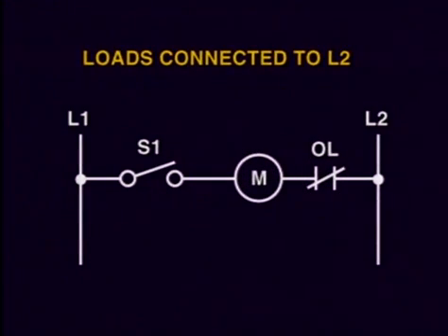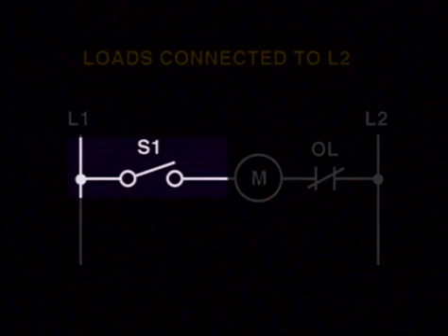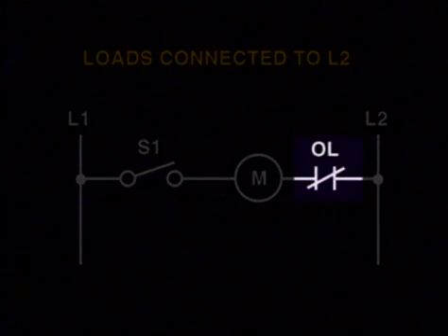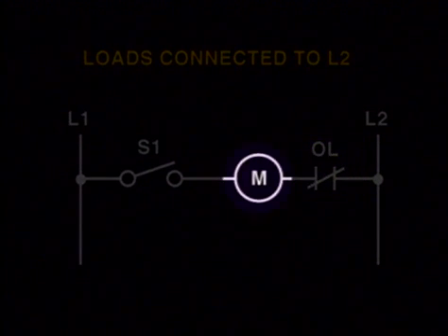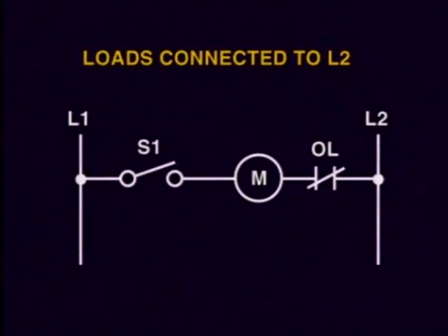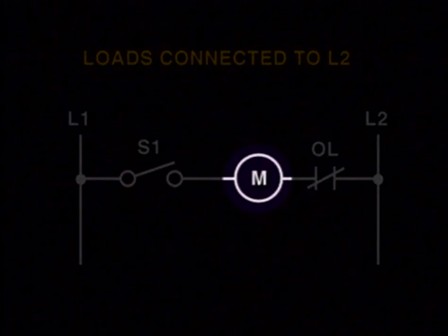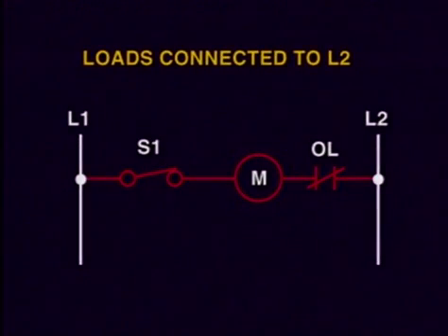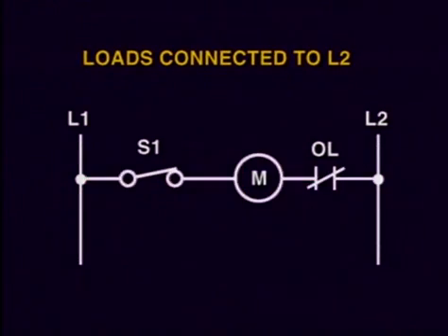As we'll see later on, the decision that governs the response of a load is represented on the left side of the load in the ladder diagram. The overloads do not really decide whether to turn on or off the motor load, but rather they monitor in a protective manner the operation of the motor. That's why we represent the overloads on the right side of the motor load. If the motor starts to pull too much current, an overload will trip and its contacts will open.